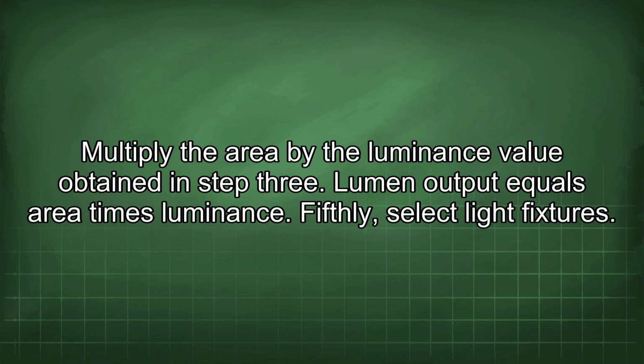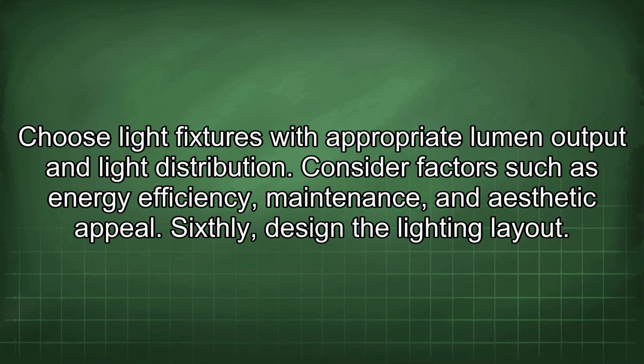Fifthly, select light fixtures. Choose light fixtures with appropriate lumen output and light distribution. Consider factors such as energy efficiency, maintenance, and aesthetic appeal.